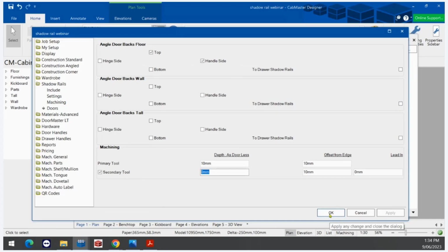Where you would use this, I'm not sure. Perhaps you want a stepped profile. You might have a 45-degree cutter, and then you want it to come back on a square edge. Totally thinking outside the box, what can I do with this? How can I do it? You can move these around, set your machining, change the tools to achieve the profile that you're after.